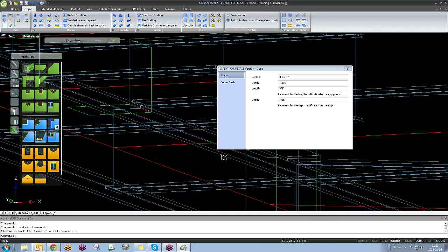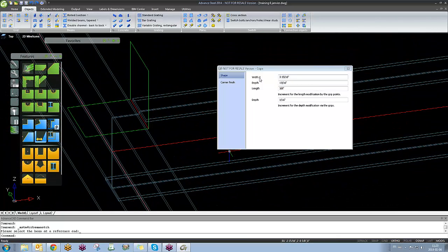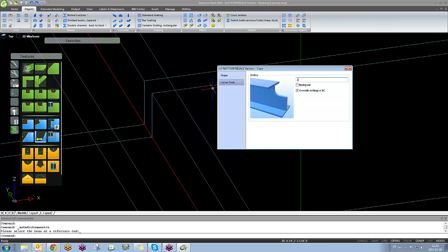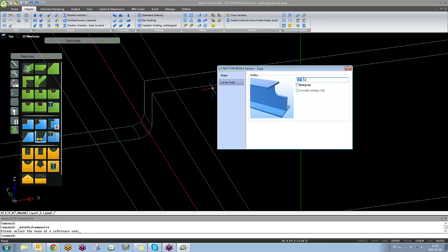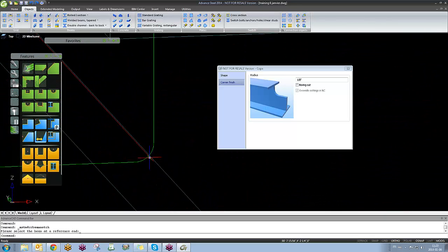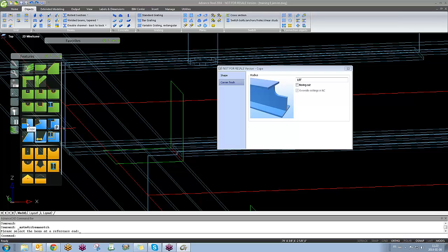Do you see the cope here? Well, you have here the width, the depth, and the length here. You have the corner finished. If you want, instead of straight corner, you want to put some radius. Well, 2 is too big. Maybe 1/8 will do the job. Do you see the little radius here? Yeah, that was it for this cope.